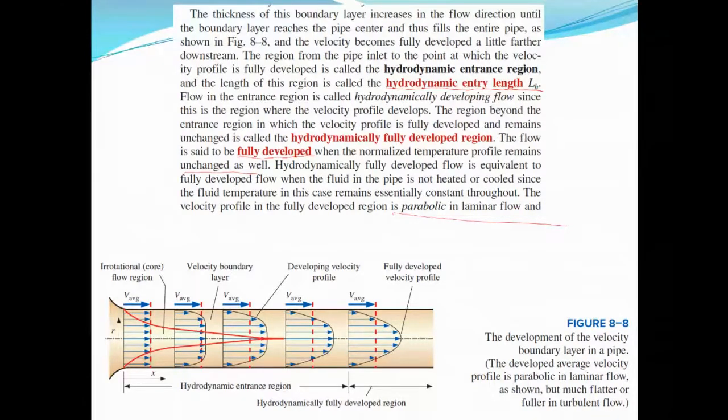Okay, so this shape is parabolic. And this is the average velocity, and we are going to see later for fully developed flow that the average velocity is simply equal to the maximum velocity divided by 2. The maximum velocity occurs here, isn't it? Because velocity is maximum in the center line. This we discussed when explaining the shear stress, under viscosity, that the velocity is maximum at the center. And here we are going to also prove that mathematically.